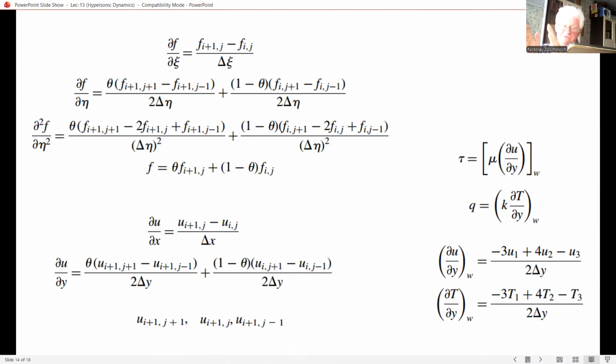When we have theta between 0 and 1, our functions f appear as unknown. And so we have 6 unknowns and only 2 equations. Therefore, the finite difference forms must be evaluated at all of the grid points through the boundary layer at station i plus 1, and as it should be simultaneous, leading to an implicit formulation for the unknown.